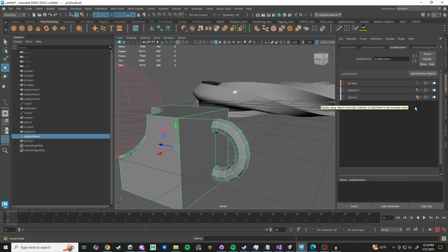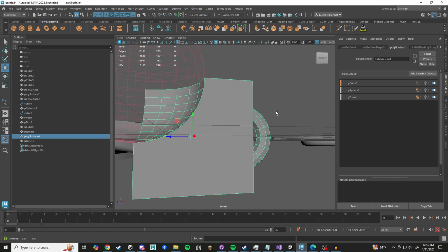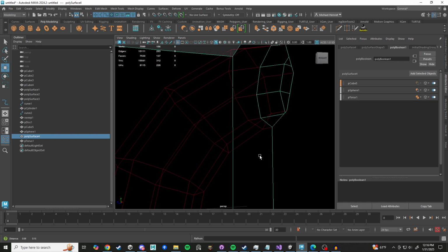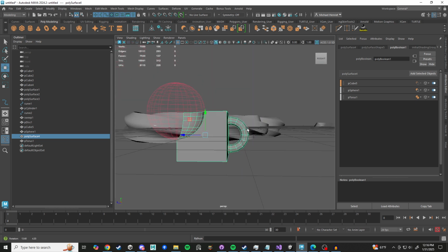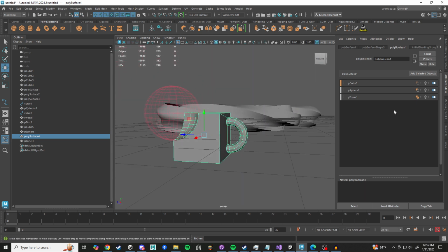This is a stack of Boolean operations now. This one is set to add, union. So this mesh on the inside, boom, got deleted. You see that? It's showing this with this red outline. It's showing where that torus actually is on the inside. But our resulting mesh does not have that. It's exactly what we want, a nice surface there.